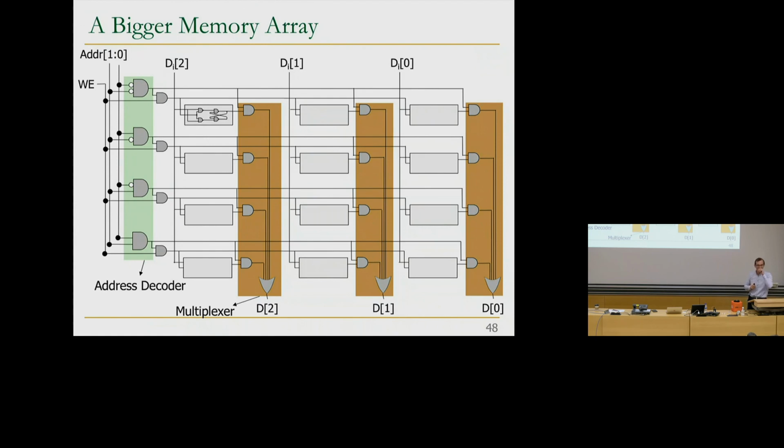Yes, one more. Why, at the end of the multiplexer, you have all of these, why do you not just combine all these? Yeah, somebody else asked that question yesterday, but basically, an OR gate essentially combines that. You could design this with some other mechanism, you just need to make it work. The difficulty is, if you have a single line and you combine everything, you need to make sure that you never load the wrong value. Basically, there's no glitch in the line. If you collect the output and go through an OR gate, you're ensuring that gate operates correctly. But if you load a single wire over here, you need to have tri-state buffers, for example, like we discussed last time, and you need to ensure that the loading is not very high on this. That's a very good question.